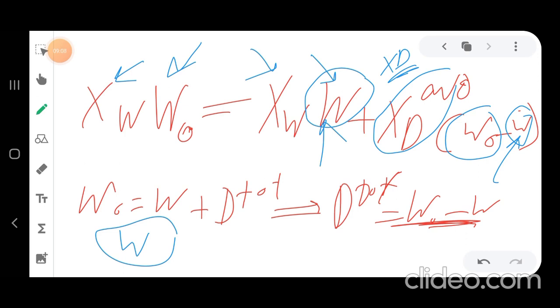So to summarize what we did, batch distillation can be done in 3 different ways. The first way is simple batch distillation, with no stages and no reflux. The second way is batch distillation with rectification, where you use stages and a reflux to maintain constant contact between the liquid and gas phases on the stages.